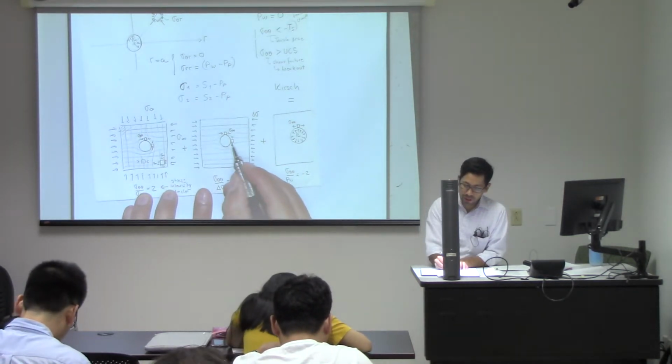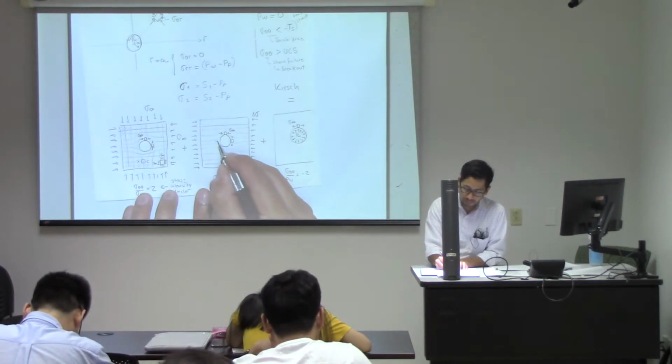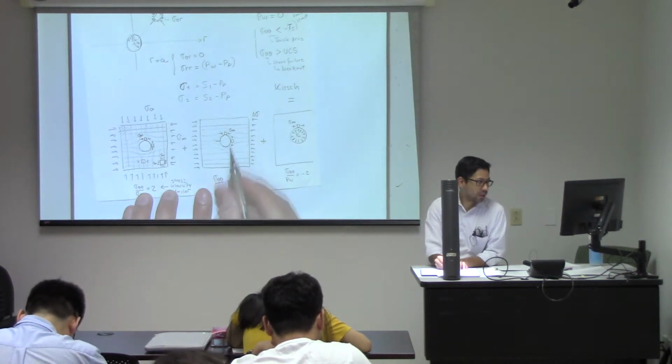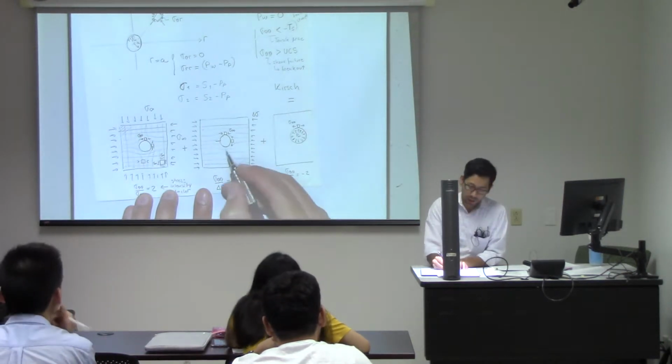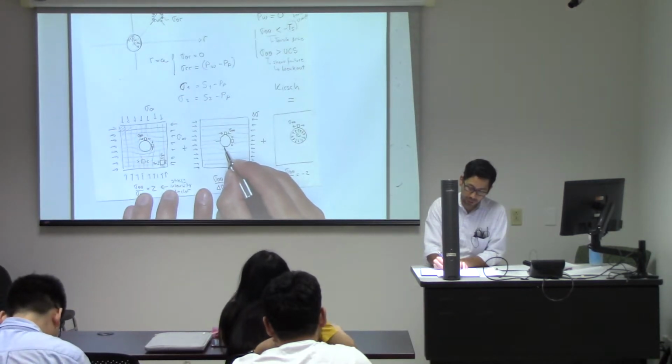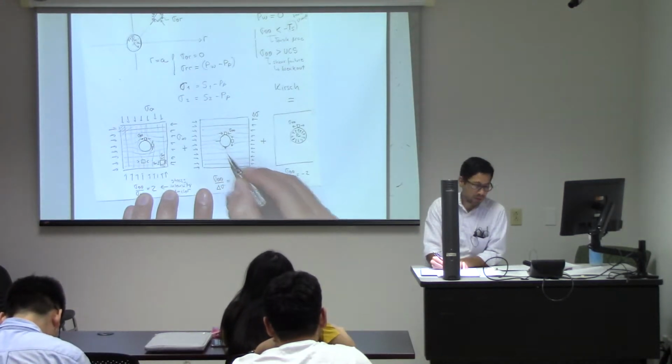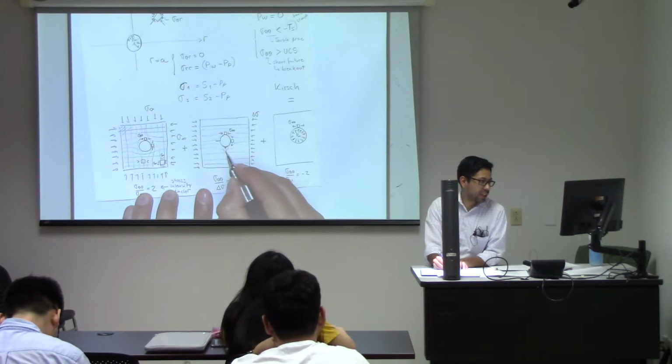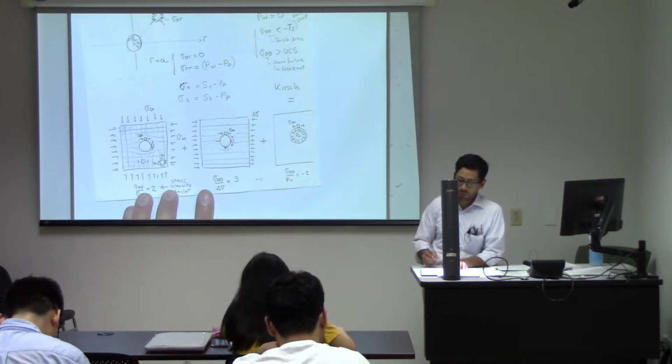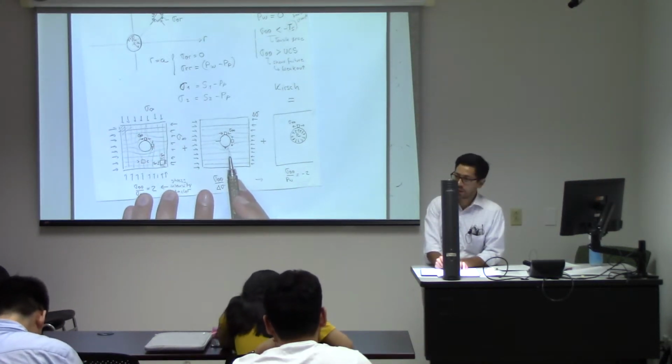So this is where you will have a tensile fracture on the other side, and in this position is where you would expect to have a compression or shear failure. And we'll explain later on why I'm drawing kind of a triangle over there.